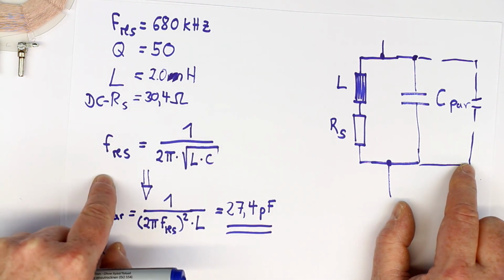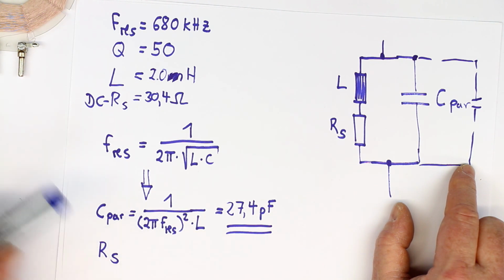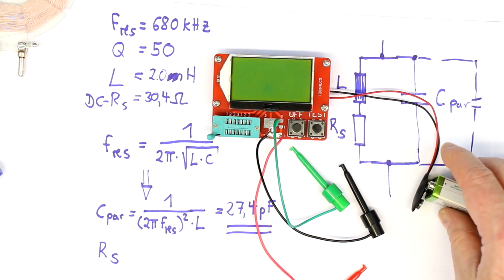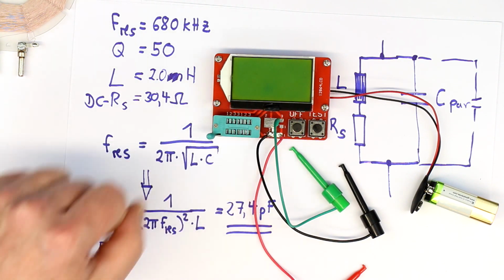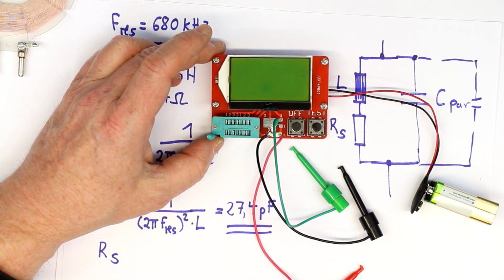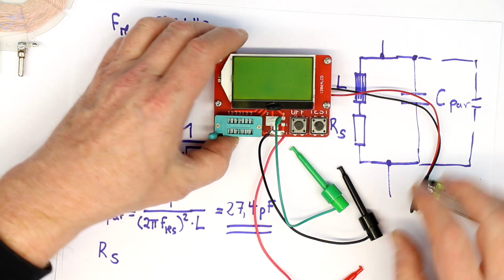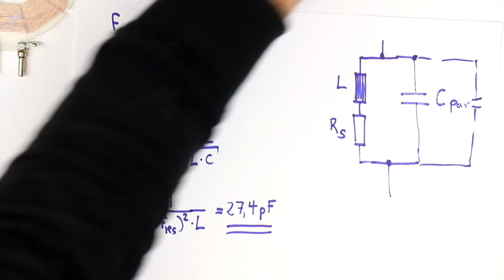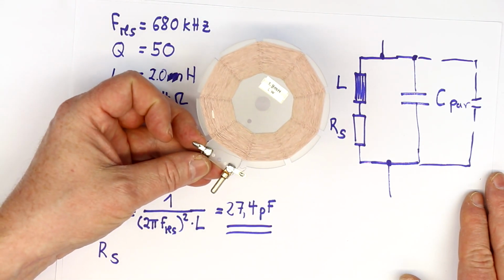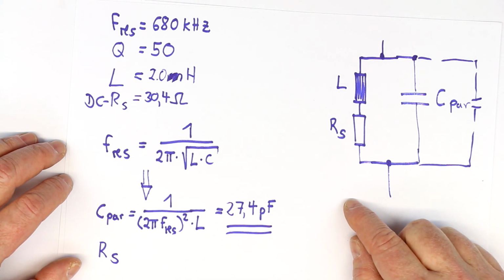And then with what's in Germany called Thomson's formula of oscillation, we can just calculate the missing parallel capacitance, and if we don't know beforehand the inductance of an unknown inductor, we just take either an expensive LCR meter or just a simple component tester from China, here in an improved version, improved firmware and improved accuracy, and with some little nice test clips here. And well, that was it for today. Perhaps something new for you to know about inductors and coils, which are nothing else but inductors, about their parasitic behavior, and that nothing in the real world is perfect.